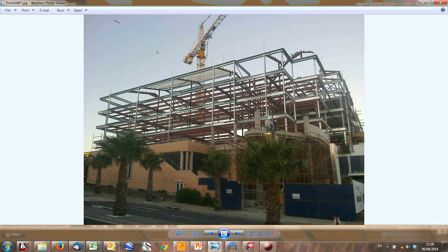And same thing with columns. You can take the areas and get a load run down and get your foundation loads. And that's why, if you can look at a structure and see where the loads are going, you're in a much better place to first produce preliminary designs. You can have a quick calc to say, well, this area, here you go, rough estimation of foundation loads, piling loads, etc. And also then, where do you put bracing, where do you put all these things?